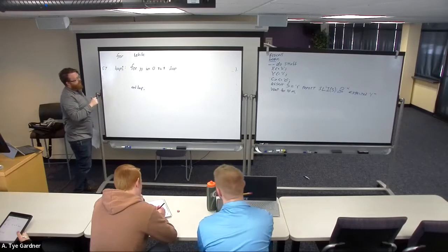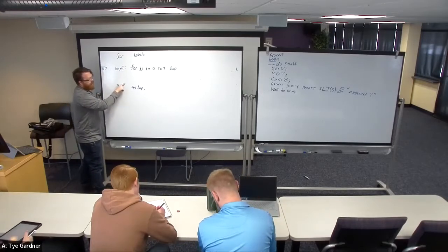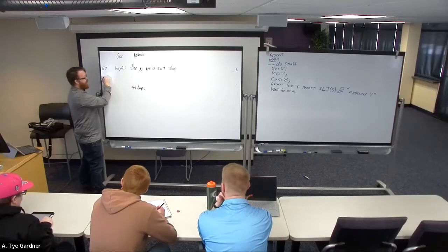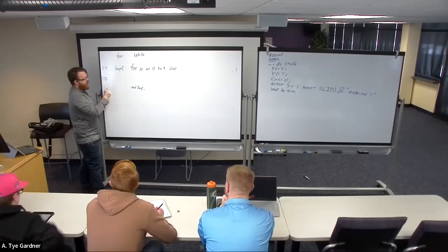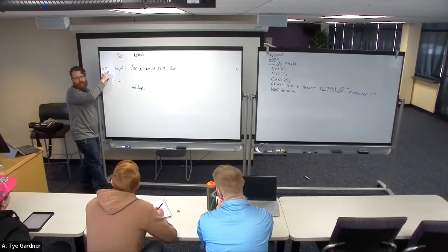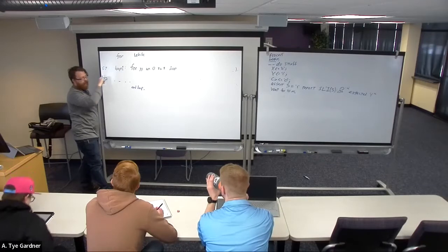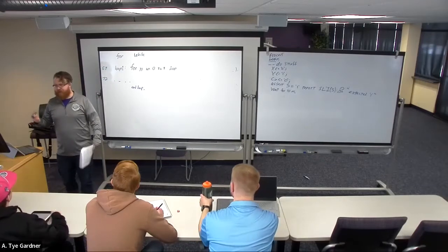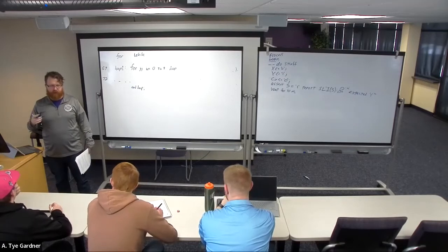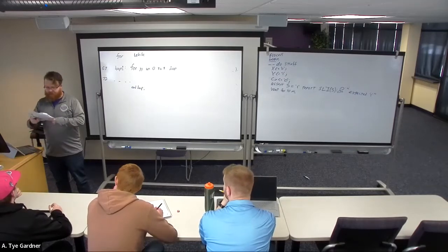One of the issues is a lot of times in your TCL console errors, if you have an error somewhere down here, say this is a big loop and this is like 72, and there's an error here, the reported error in the TCL console will often report the loop as its error, so then you have to go look in. So hunting down where the error actually comes from is something of an art with VHDL and most programming languages. So just keep that in mind as you go through.